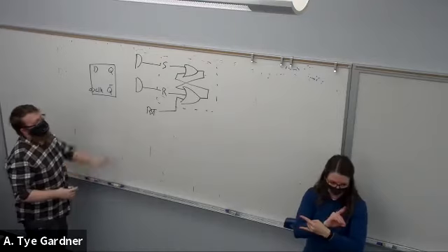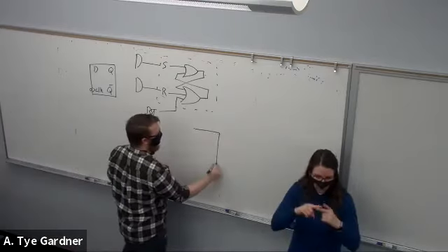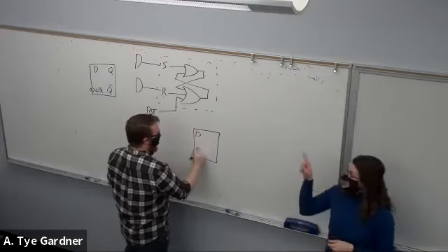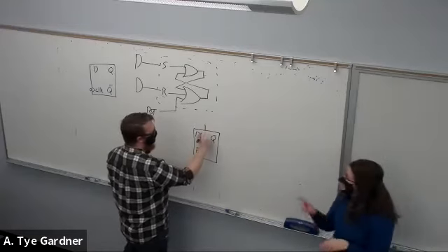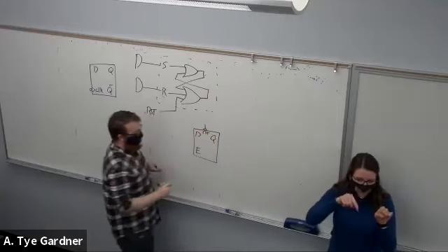You don't have to worry too much about that. It's really simple. When we convert that and go through all of those same steps, which I'm not going to do for the D flip-flop, you'll often see it on the top or bottom labeled RST, and very frequently there are active low resets.